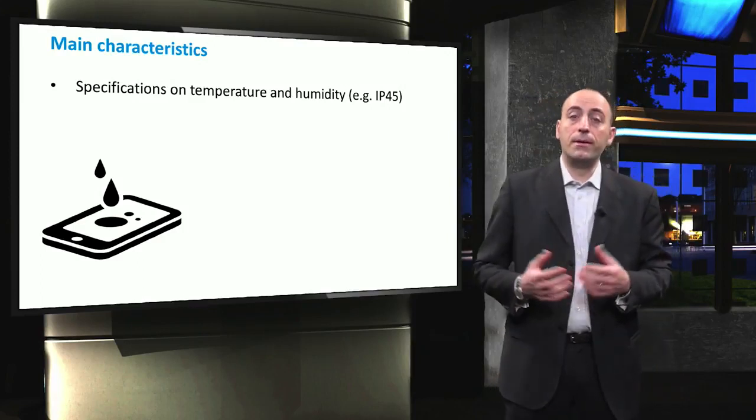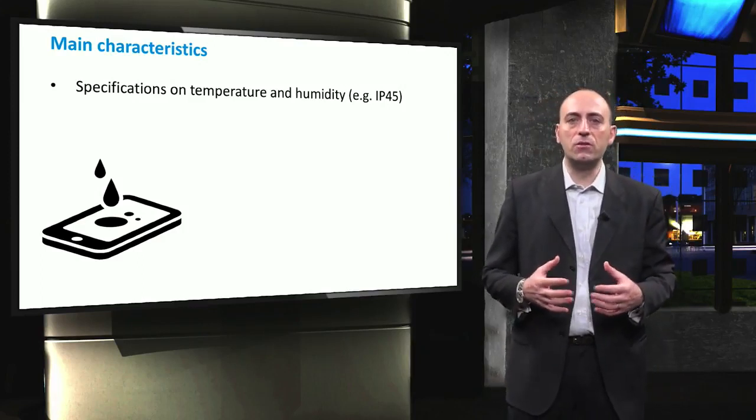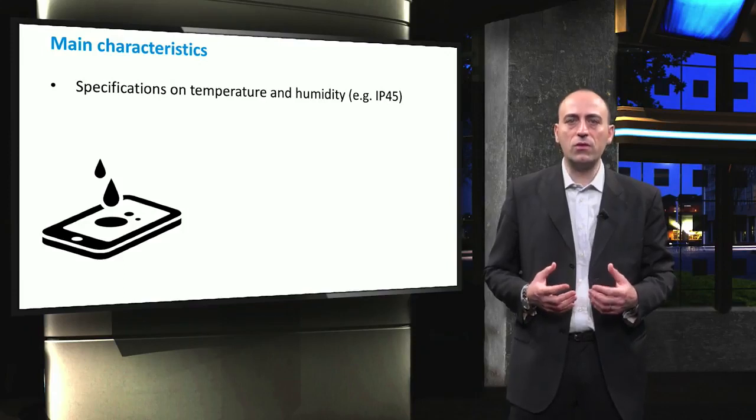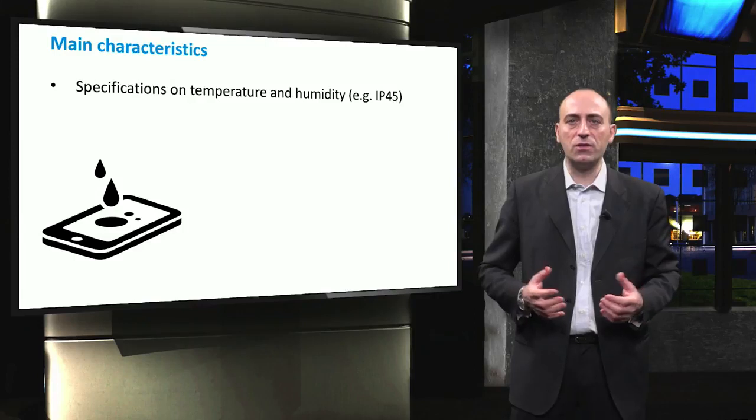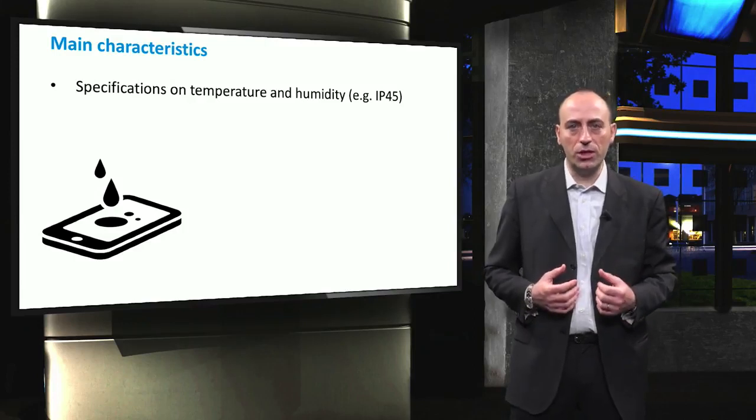The goal is to minimize the unwanted influence of electromagnetic interference on other equipment in the vicinity of or connected to the same supply. Then, in many instances, the PV system needs to be installed outdoors, and the inverters should meet certain specifications regarding temperature and humidity conditions.